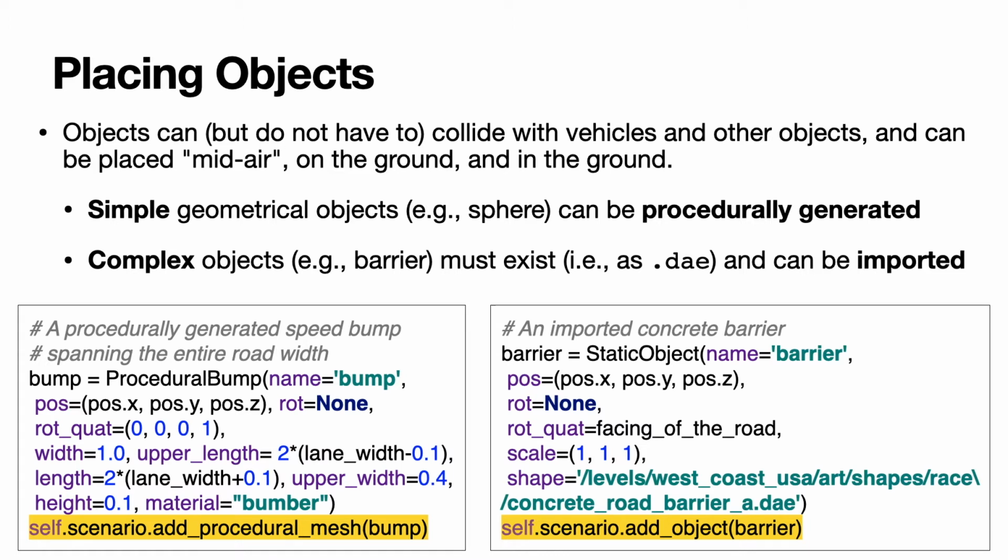If you don't attach material to them, they will appear in some default color. They will exist, and they will crash your car if you bump into them. But you can also specify additional material. You look up the material inside the distribution, in the folder named art, you select the one that you want, and then you attach it to your object.